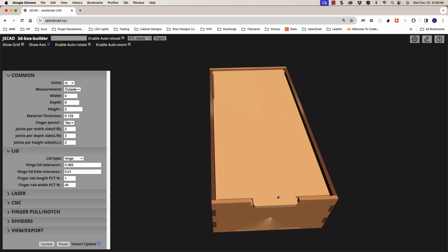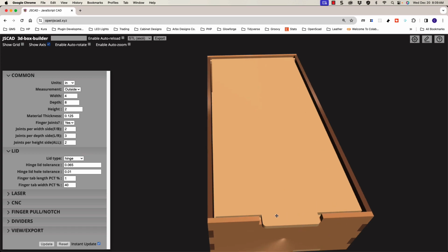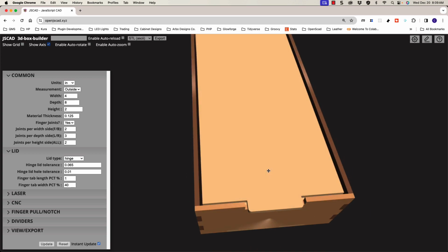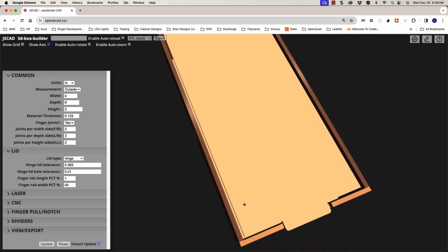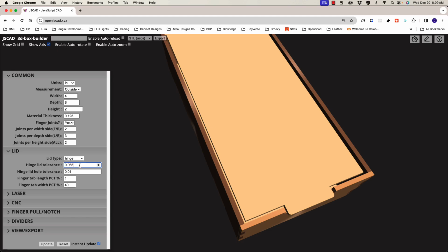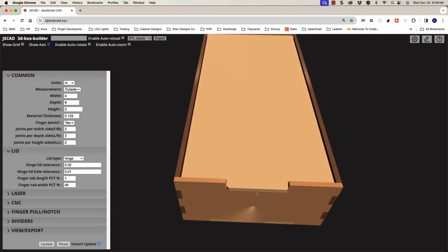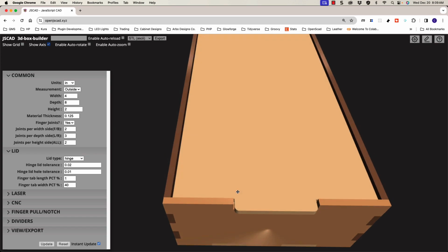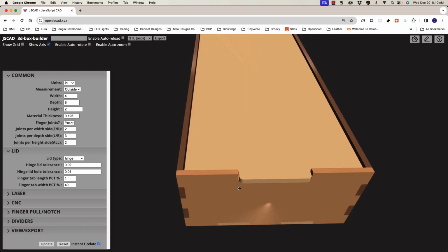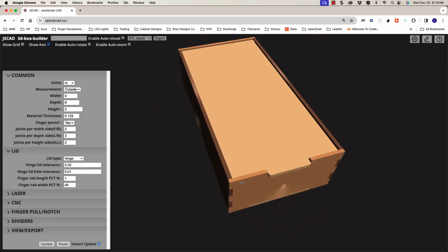With laser, this is not a big deal. It just cuts and you're pretty close except for the kerf. So keep that in mind, and that's why this is pretty wide. For laser, I might go 0.02 for tolerance, and it tightens that up, just looks better. And you can see I got a little gap, that should be fine. Yeah, so those are some options there.